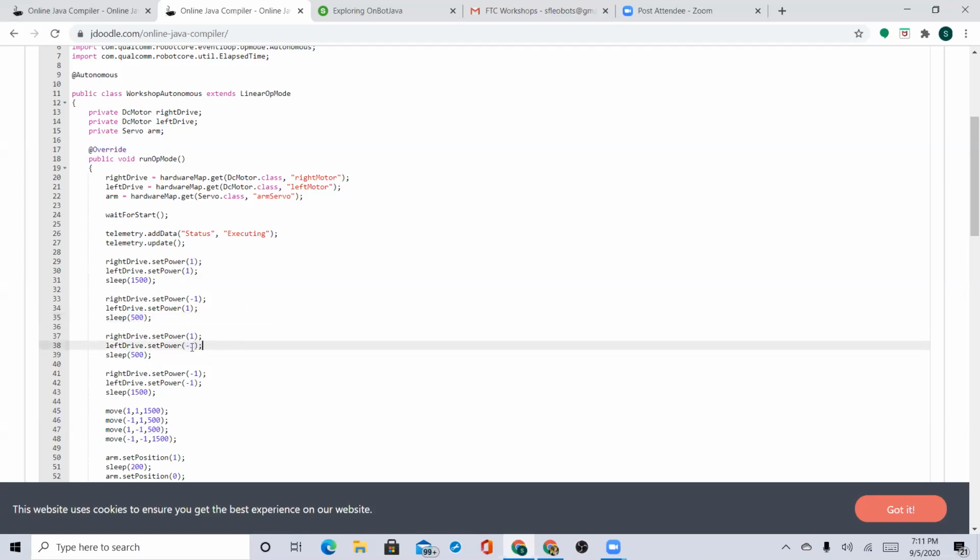Now, I am essentially reversing that. Now I'm turning to the left. Since my right motors are moving forward and my left motors are moving backward, I'll be turning to the left, and that's for 500 milliseconds as well. So again, if we were to visualize it, our robot has moved forward, turned to the right, and then turned back to the left, so it's facing straight again.